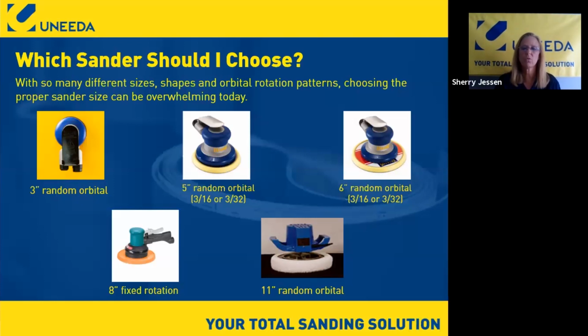With the cornrows, as the light shines across, you'll start to see the pattern in which you sand. It's one of the reasons why we try to do figure eights or random patterns, but you can still see everywhere you move the sander. With the 11-inch, especially on a large piece, the 11-inch eliminates that. So that's kind of been the go-to with solid surface.